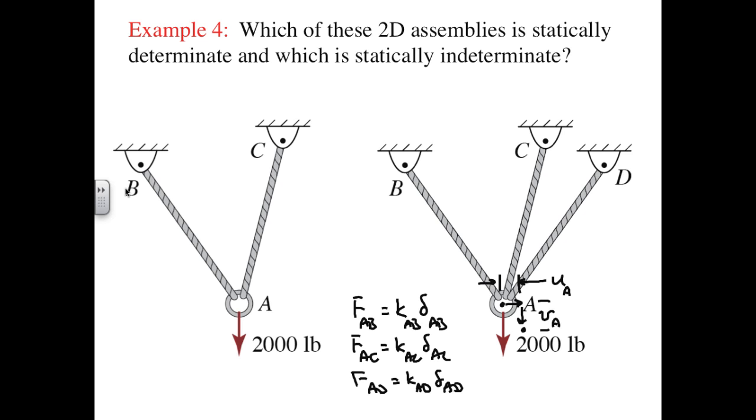For now, it is enough to be able to classify problems as statically determinate or statically indeterminate, and to recognize that the equations of static equilibrium are no less valid in a statically indeterminate problem. The equilibrium equations must be supplemented by so-called compatibility relationships, that is, force-displacement relationships like F equals K delta, in order to find a solution in statically indeterminate problems. Let's now try a couple of spring problems, and then we'll return to particle equilibrium and examine some three-dimensional problems.